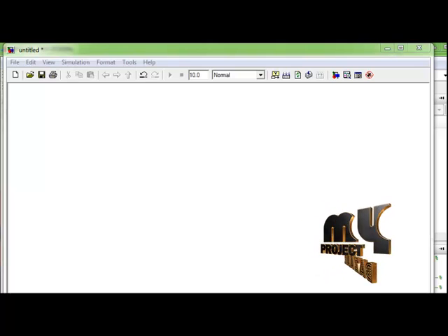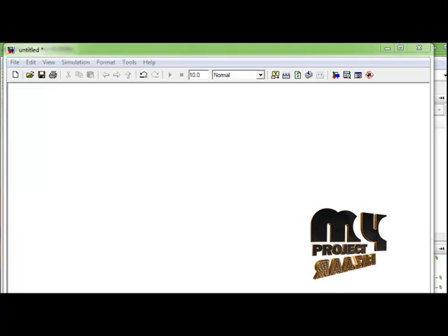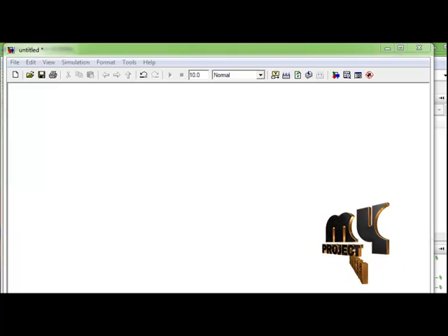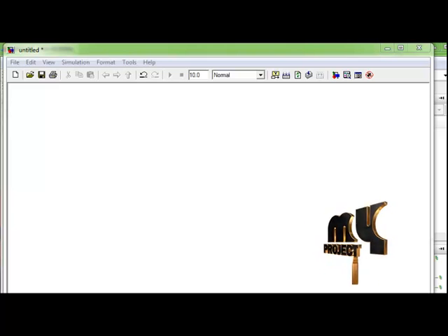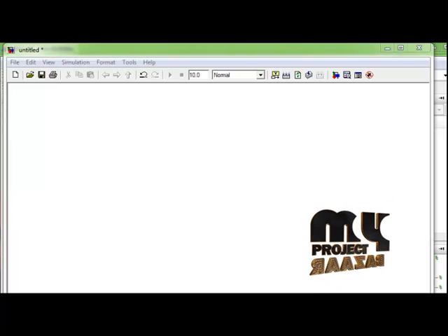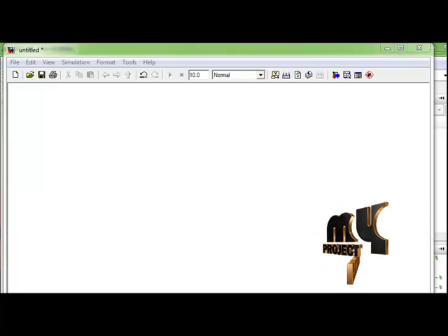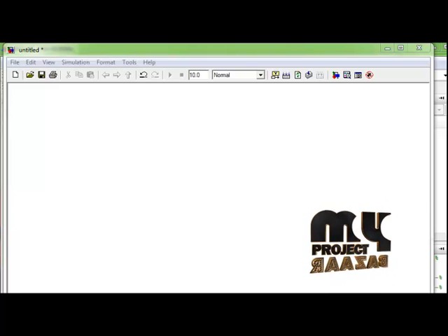From this we conclude that the inverter current control of a grid connected single phase photovoltaic inverter has been proposed. High quality current is also injected into the grid. The proposed method uses an RLS adaptive filter to estimate a particular harmonic in the grid current that needs to be attenuated. To avoid DC biasing of the transformer, a novel PRI controller has been proposed and its design has been presented.